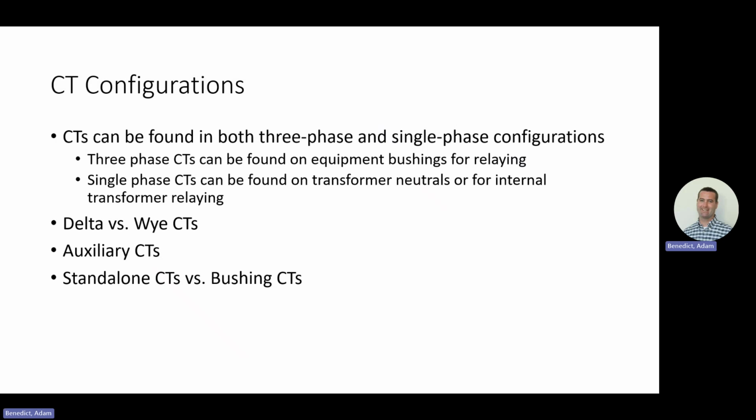Trying to think of other single phase CTs. Metering could be single phase, but yeah, 9 times out of 10 it's under transformer neutral. Or you'll see it for transformer monitors too. They'll have a single phase CT for the LTC, your load tap changer.